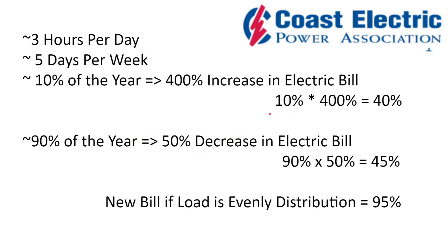So let's assume you're either having a solar array that's on during peak times, or having a battery that runs during peak times, or, what I do is I use my home automation system to change my thermostat settings and turn my heavy appliances like my electric water heater and refrigerator off and coast through the peak time. So I solve this issue without solar or batteries. And that gives me about an even load distribution, without solar or batteries during those peak times. So I do some load shifting to reduce my energy during peak times in an automated fashion.